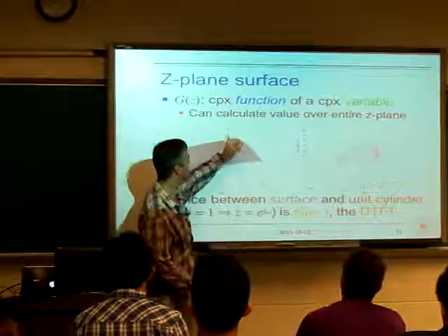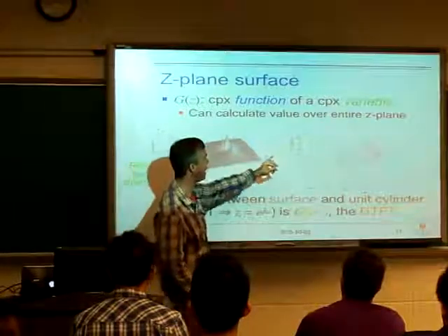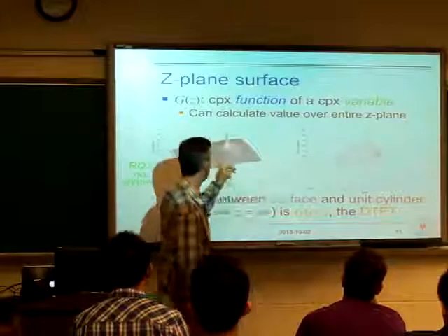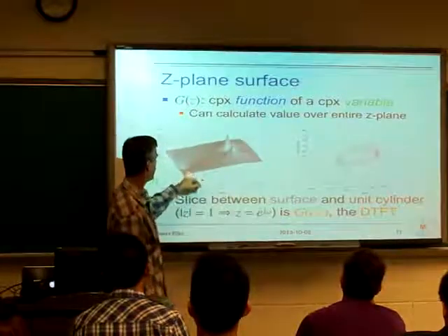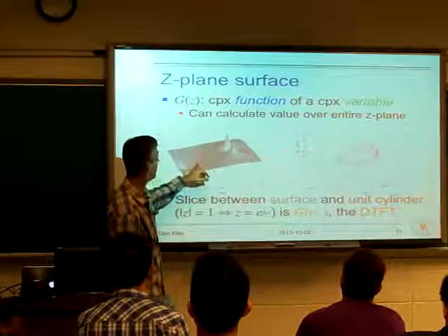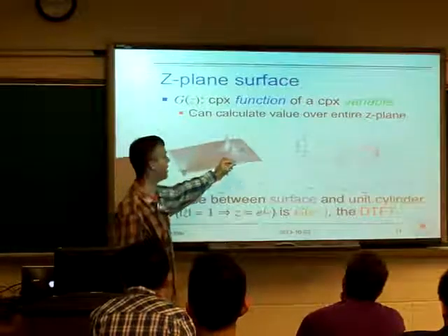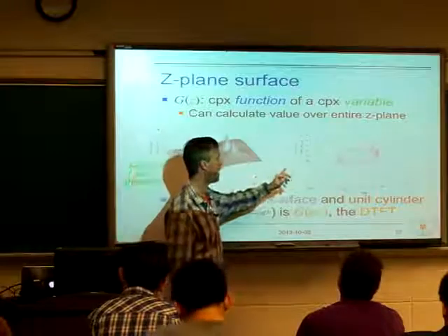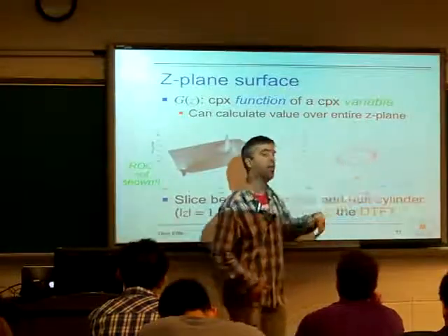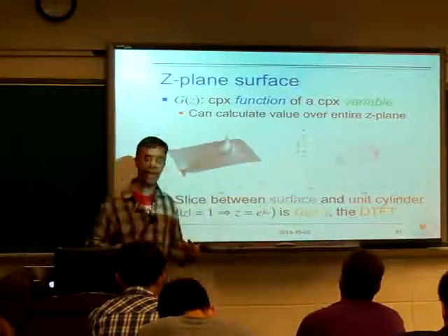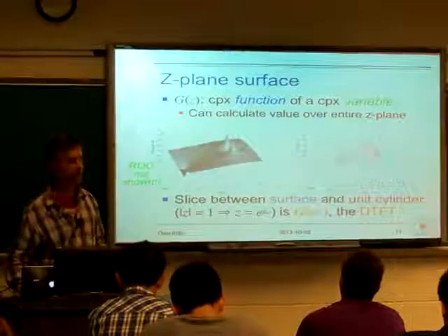Knowing where the poles and zeros are in relation to the unit circle, this dip here is because we're approaching this zero down here. We can guess how they're going to interact with the unit circle. That will then tell us what the Fourier transform is going to look like, and then we quickly get an insight or a rough idea about what the system is going to do.